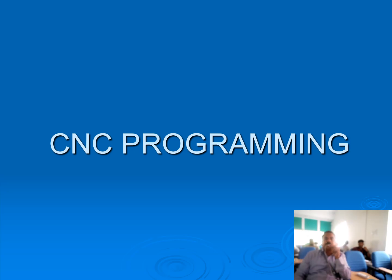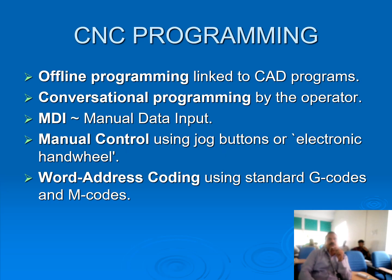The CNC programming. When it comes to CNC programming, there are offline programming linked to CAD programs, conversational programming by the operator, manual data input MDI, or manual control using jog buttons or electronic handwheel, and word address coding using standard G codes and M codes.